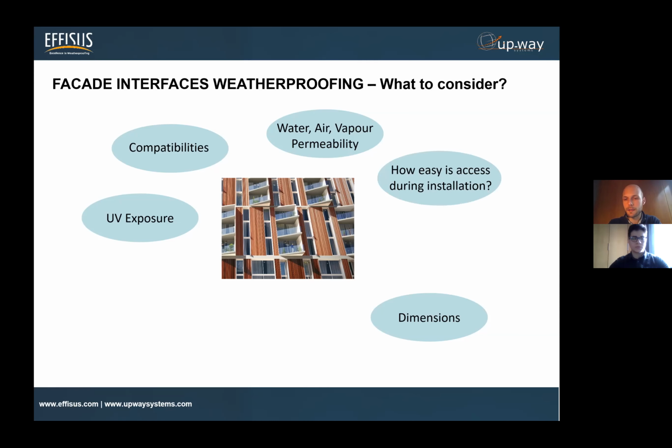How easy is access during installation? Because we cannot only choose our solution based on a paper or how the interface should be done or what's the width that you have available to bond the membrane. No, we really need to understand how it will be installed at site. And it's really important to help people on site reduce the risk during the installation, for instance, reducing the risk of committing any errors in terms of using wrong accessories.